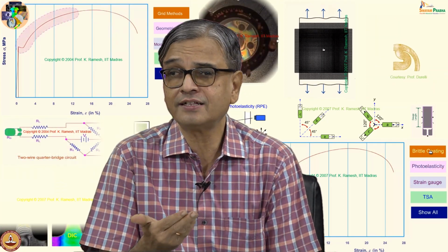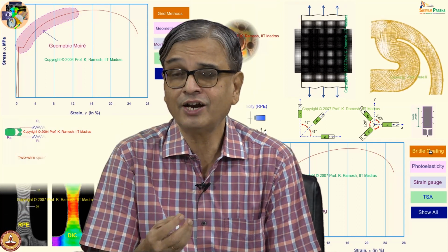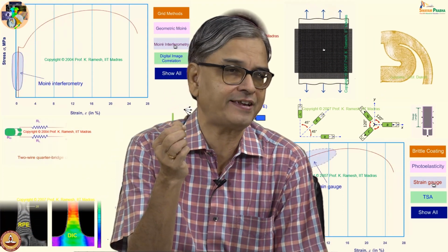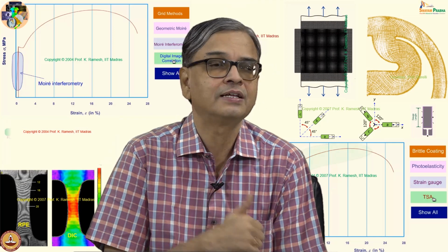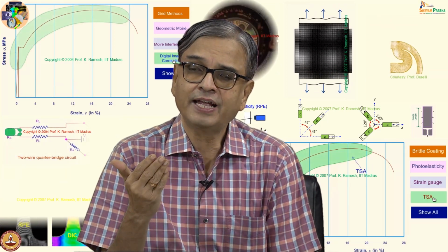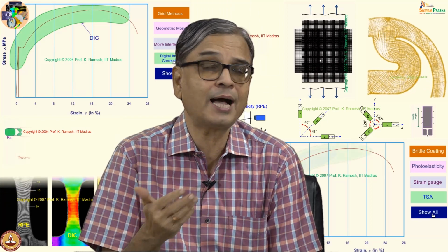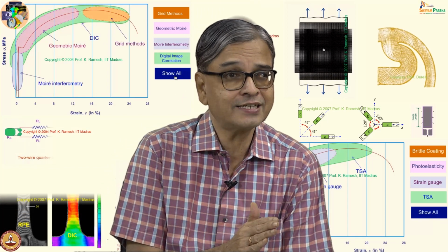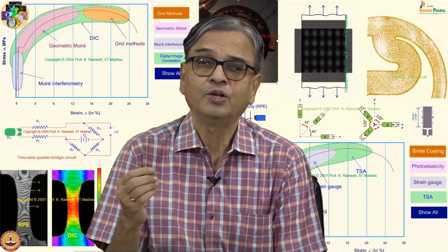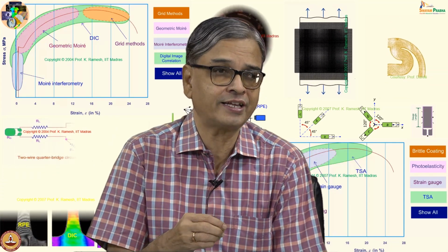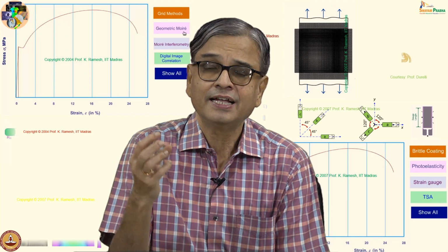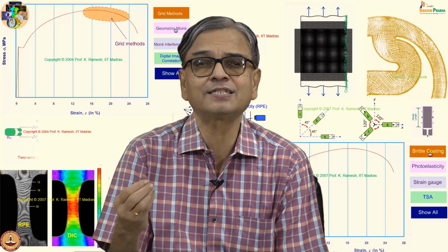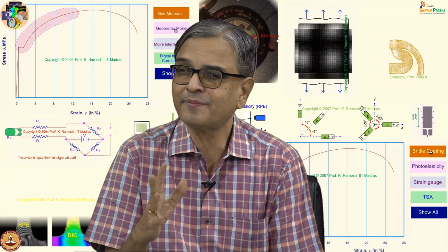Why do you have to study the strain sensitivity of a wire? We have to understand why you make a strain gauge as a grid. Why not have a simple speck of material to give you strain? That is one issue. Another issue is, when I want to paste a strain gauge on an object, a priori I do not know what the level of strain is. Is the idea clear? It can go from the elastic region to the plastic region. When I want to interpret the data from the strain gauge, whatever the calibration constant that I use, it should be the same for elastic as well as plastic ranges. Otherwise, I cannot make a measurement.